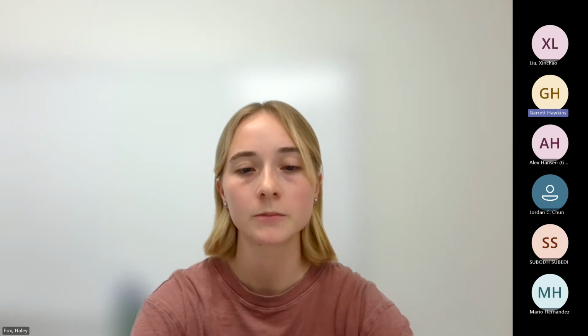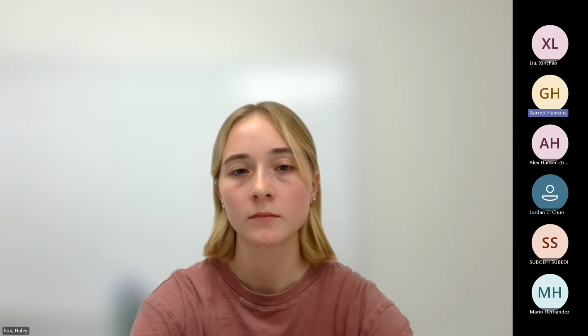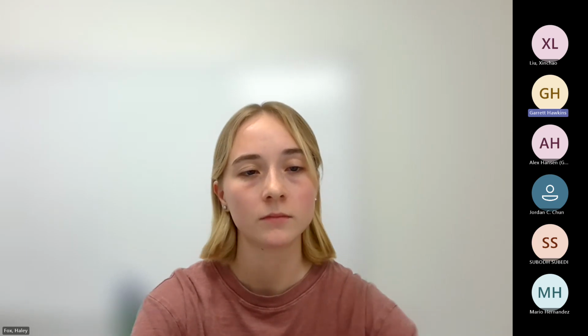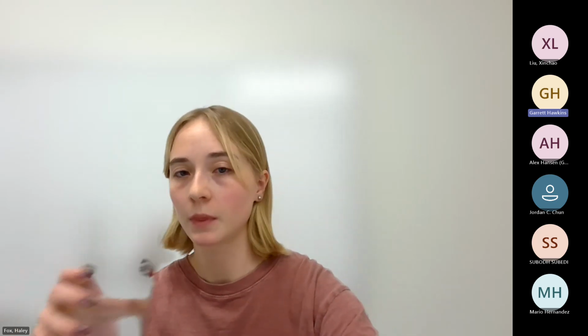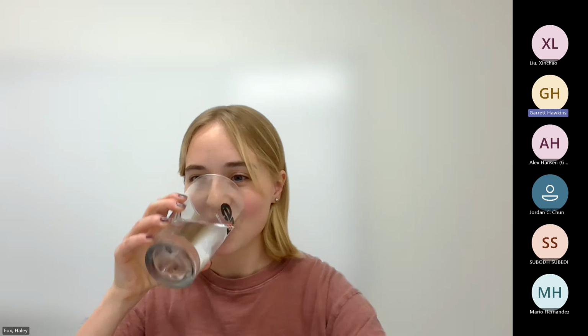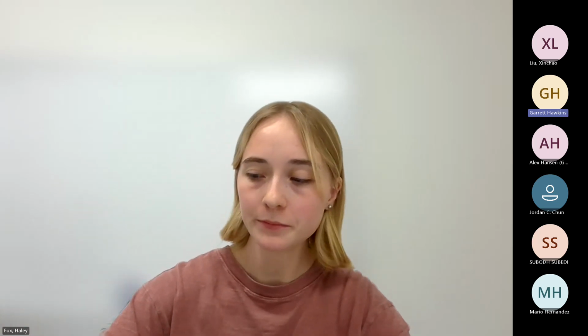Because all of that post-processing, that's hand touch time. And a technician or an engineer who's doing that, that's very, very expensive to add to a manufacturing process, as well as it's just another opportunity for something to break. If you're taking a file to a support structure, or you're taking tools to try and get powder out of an SOS part, that's just more and more opportunities for that part to break. And then you have to start a whole other build again.